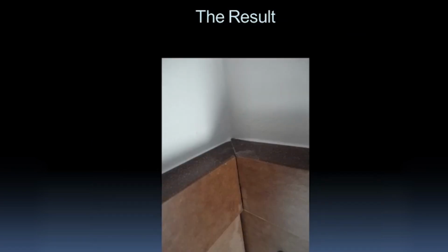This is one of the many results. This is a wainscot, and you see the top rail of it has already swollen and opened up. Of course, you also notice it again. The painter didn't have any problem just going ahead and caulking that and getting his painting done. And this is present throughout the project.